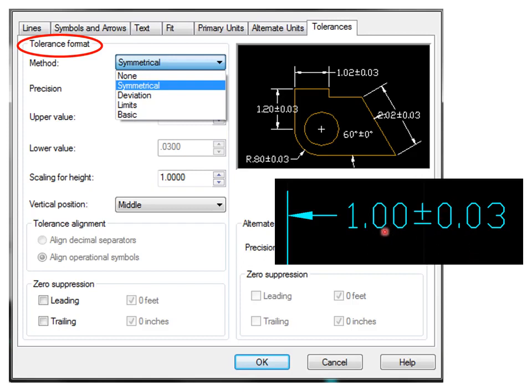So here you're telling the machinist that from the 1 inch thickness, you can be off by 0.03, or 30 thousandths of an inch, in either direction. This is the wiggle room you give the machine shop and also the inspector. When the inspector measures the thickness of the plate that was machined, they want to know how much they can be off by, and that's referred to as a tolerance. Again, we'll talk more about this in a later chapter. Next slide.